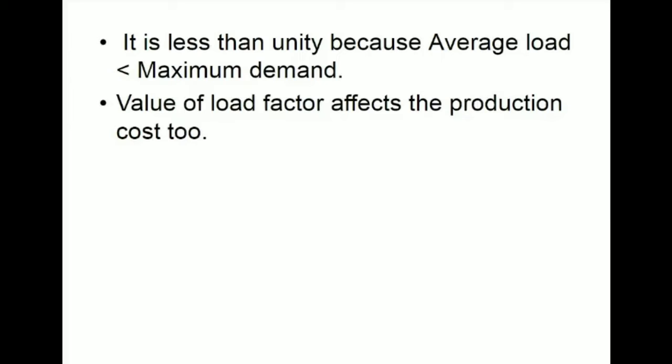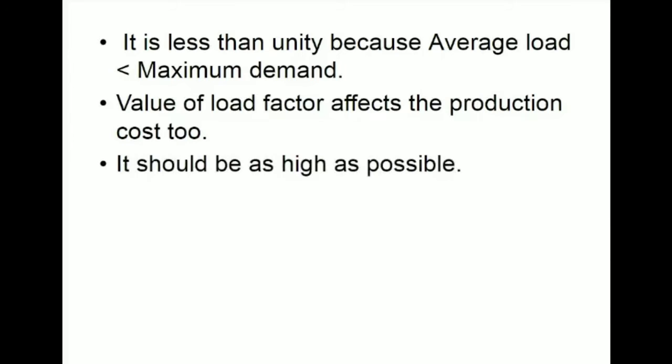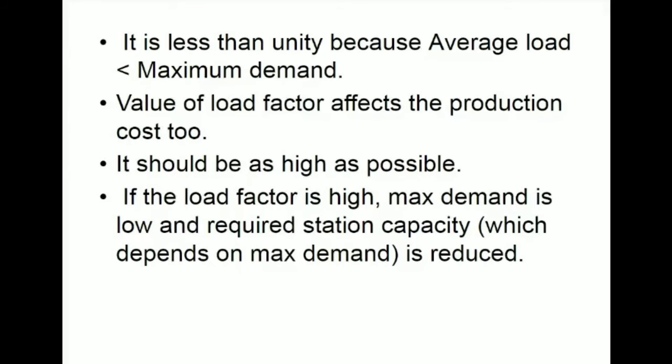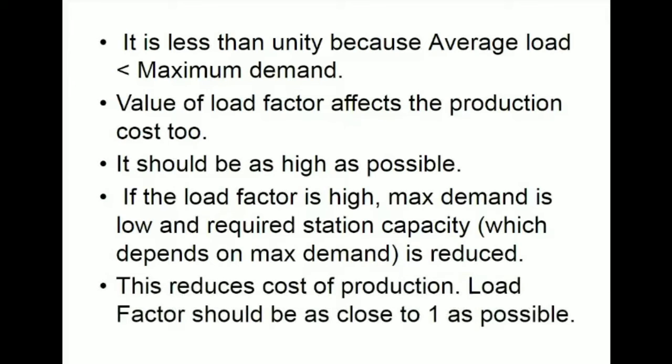The value of load factor affects the production cost also. It should be as high as possible. If the load factor is high, maximum demand is low as per the expression for load factor. And the required station capacity, which depends on maximum demand, is reduced due to this. This reduces the cost of production. Load factor should be as close to 1 as possible.